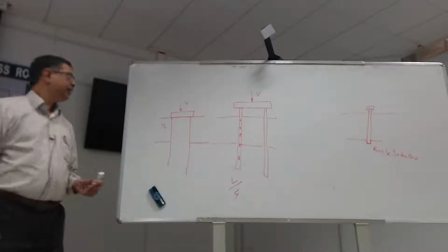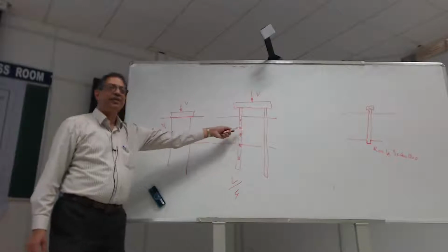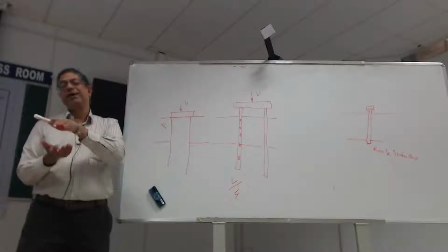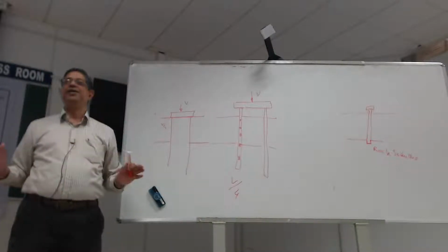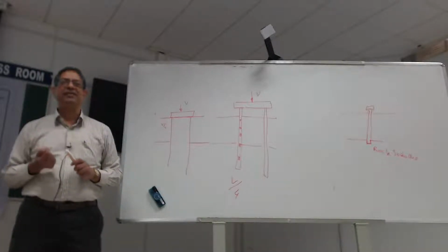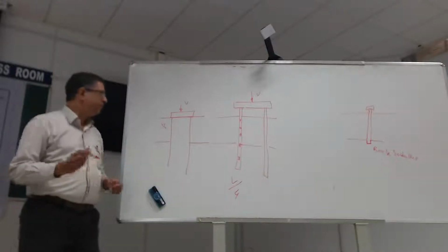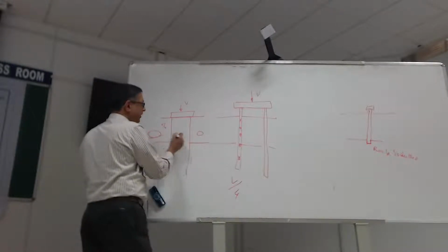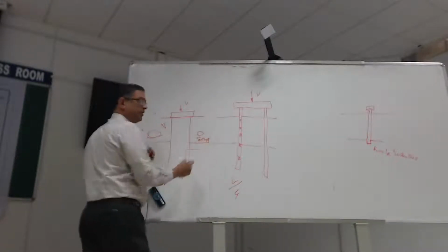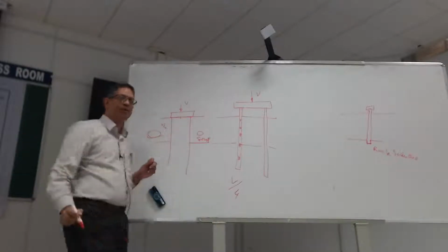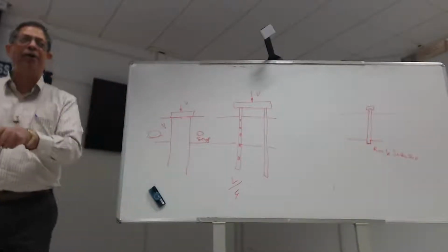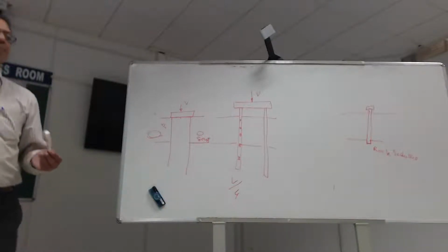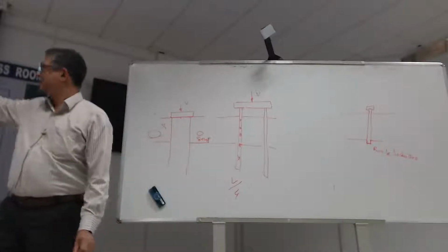That means, what's the difference between these two? This guy, right? So now he's in contact with the pile cap, which means if the pile group wants to settle in, he'll say, no, I'm going to give you my pile cap capacity. So briefly, while it's all turned into soup due to liquefaction, the only thing helping you is the thing you ignored as part of your factor of safety calculations in the static design. Imagine you don't have the cap, you'll be getting stuck with that one.